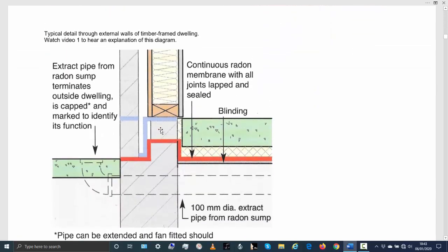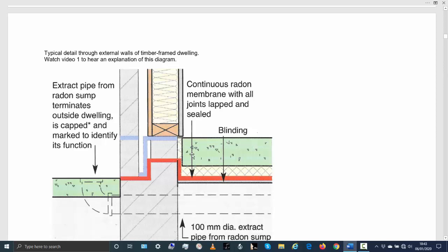And at the ground floor, that's typically what your structure will look like. Here it's shown correctly in that you've shown masonry. This blue here is DPC, damp-proof course, and that damp-proof course stops rising damp. It's basically a plastic membrane. It stops rising damp going through the wall.